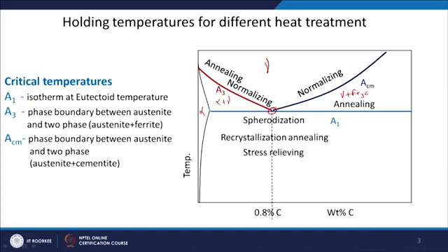If you remember, I will just show you very quickly. This was the spheroidization temperature, we did not cross the A1 temperature. So, there is no phase transformation which has started. Cooling rates are important only when you are having any phase transformation. In this case, because we have not crossed the austenite, we are just doing annealing at a temperature below A1.